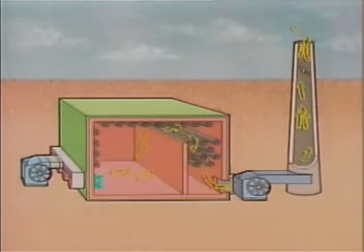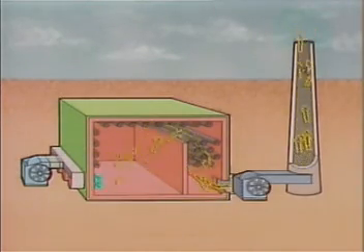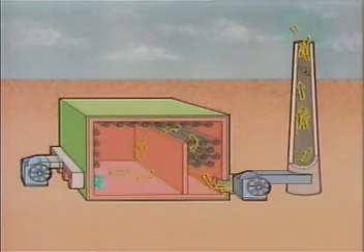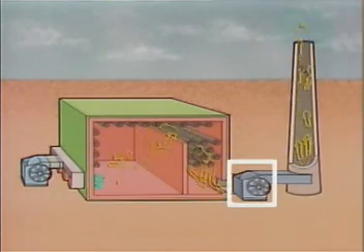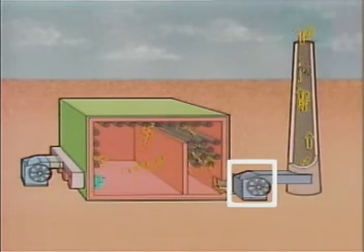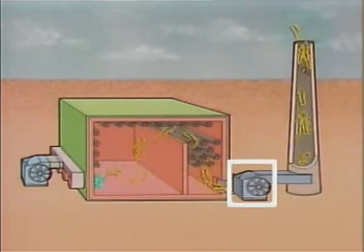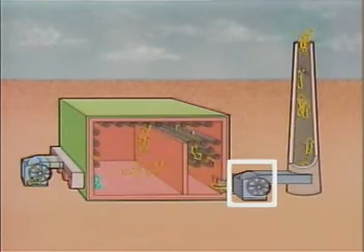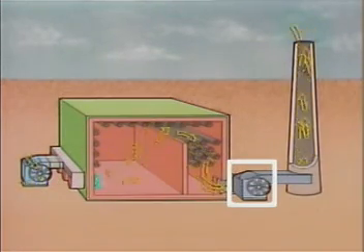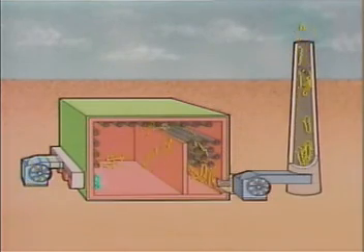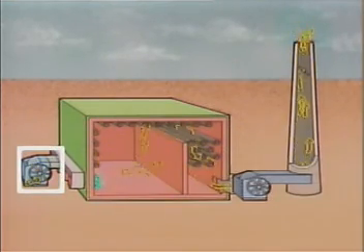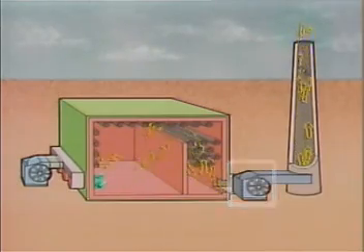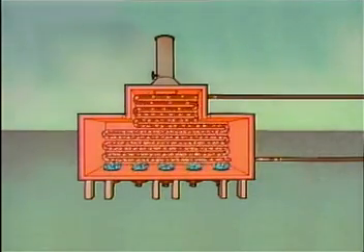One type of furnace is a balanced draft furnace. A balanced draft furnace is similar to a forced draft furnace, but it has another fan in addition to the forced draft fan. The second fan is called an induced draft fan. It is located in the flow path of the combustion gases between the furnace and the stack. So, in a balanced draft furnace, one fan provides air for the burners, and the other fan removes the combustion gases. This particular furnace is floor-fired.